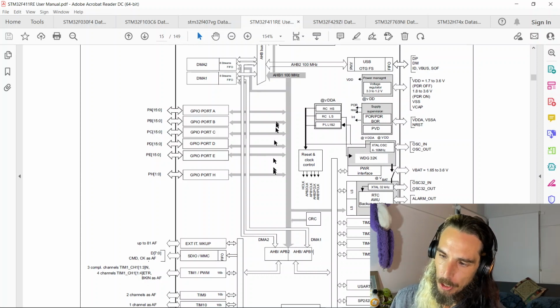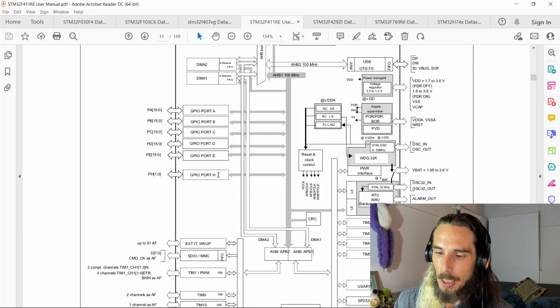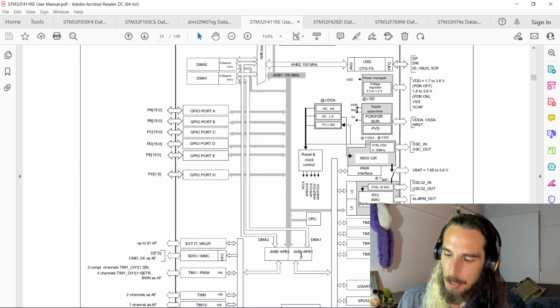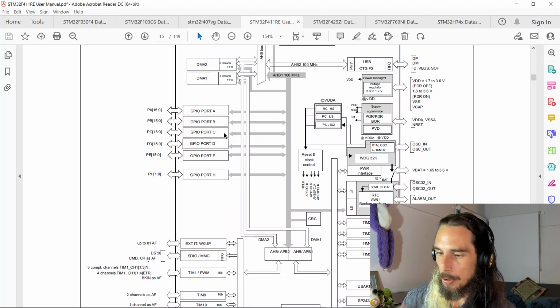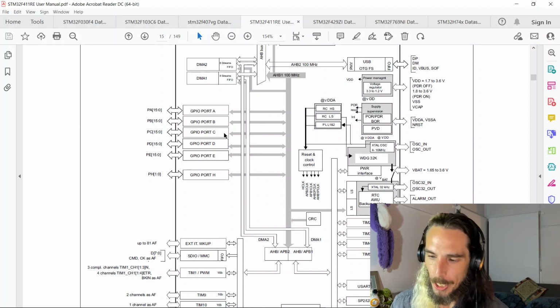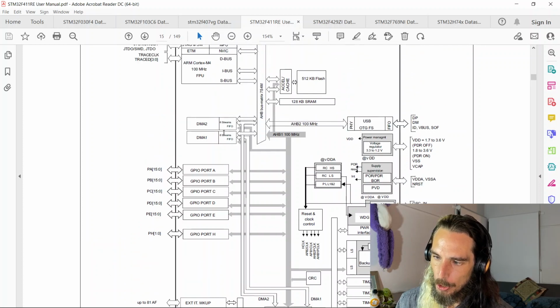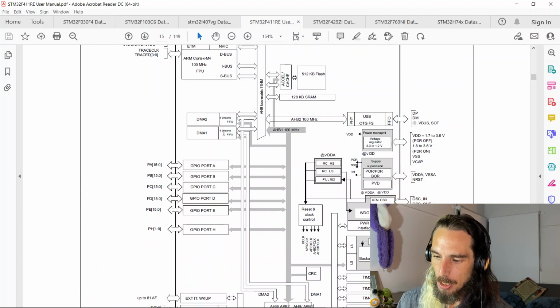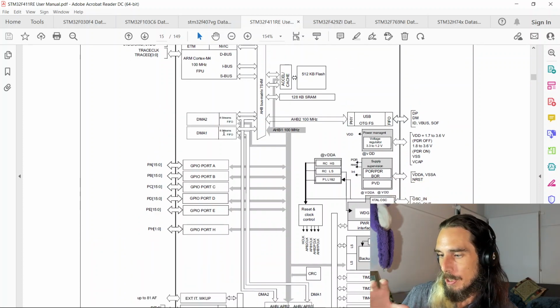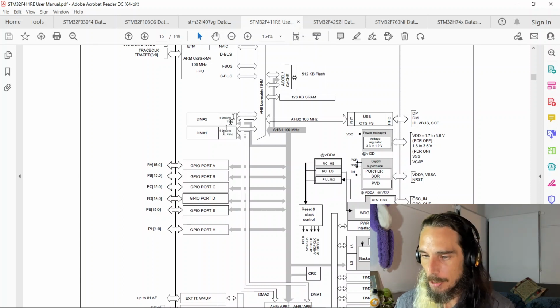We'll also notice that the host bus is connected to our GPIO ports, which is good because it means that it's not going to have to go via the bridges in order to toggle pins and do that sort of stuff if we're just doing standard GPIO input or output. So that's how you'll find most of the various components within most STM32 devices in the family connected.